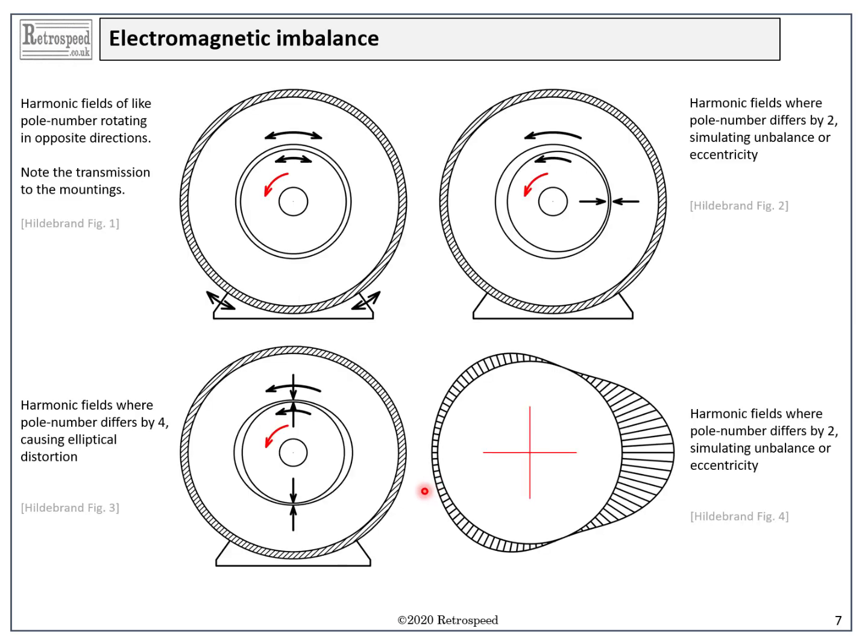In the next slide, we can see why this is such a good introduction to the subject. On the right-hand side, we see the effect of a radial force resulting from two rotating flux waves whose pole number differs by 2. At the bottom is a construction showing the typical shape of this force field. Of course it is idealized, but the main point is the resultant unbalanced pull in one direction. Depending on the origins of the field, the resultant force can rotate in either direction, and it can even be stationary.